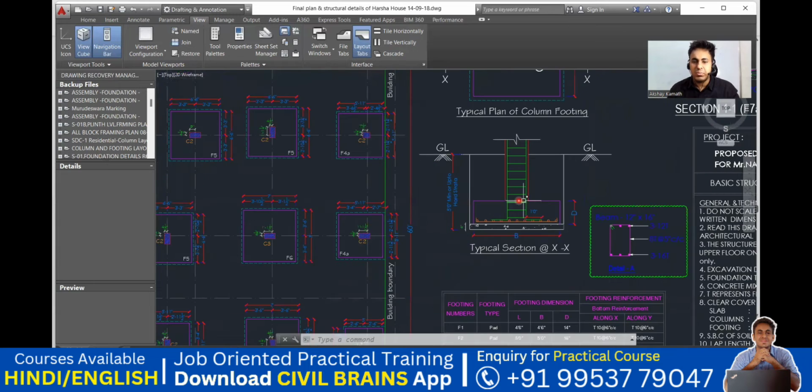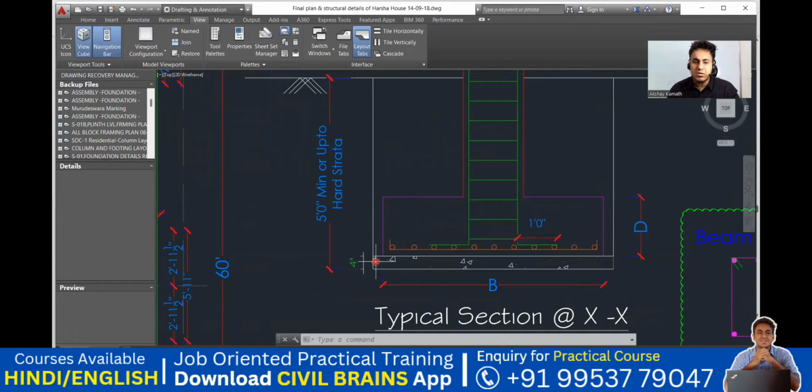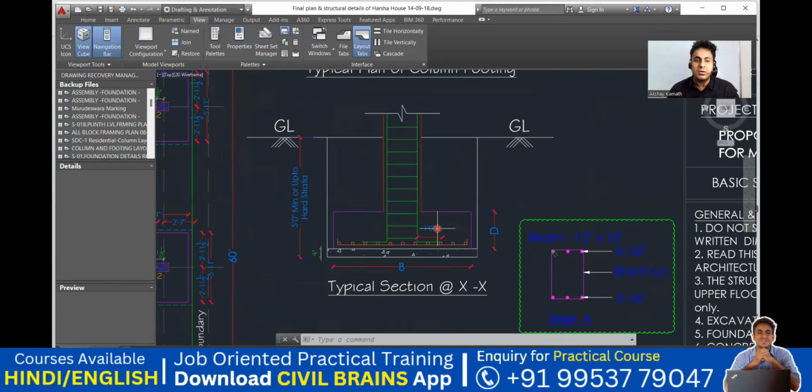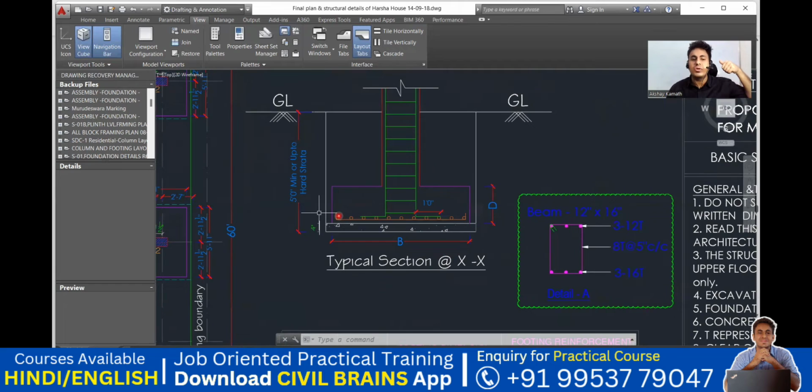So this is that particular bed concrete, what you can see. It is 4 inches, as mentioned here. And your depth of excavation will be 5 feet, which comes out to be roughly 1.5 meter. So this is your depth of excavation. Up to here, 5 feet of excavation will be done. Then the PCC bed will be put, and then the footings are going to come.